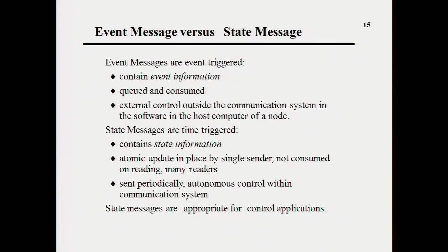Every time you have free time, you consume an element in the queue. Now, of course, this is why it is non-deterministic, because this queue has to be finite. I cannot have an infinite queue. And so if for some reason the data come in really fast and I'm slow to react to this data, it so happens that at some point something gets dropped or something gets overwritten. And so I don't know. It's non-deterministic. Behavior is who knows, right?